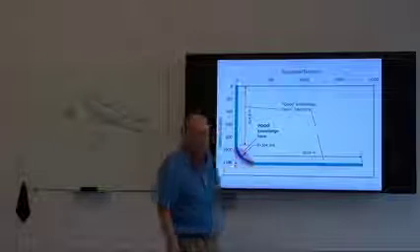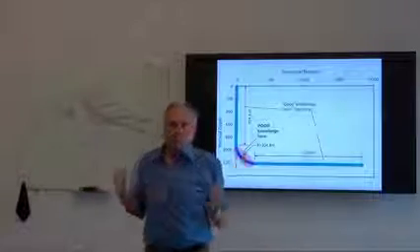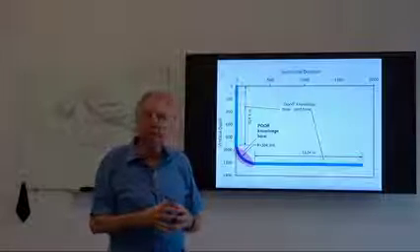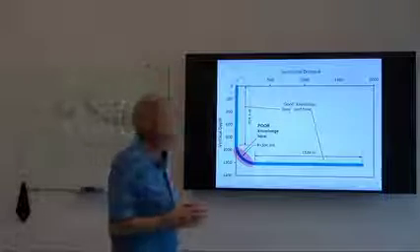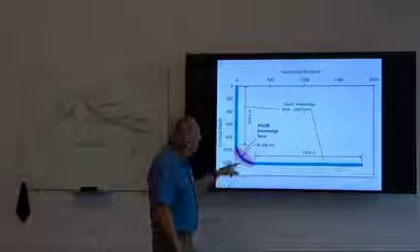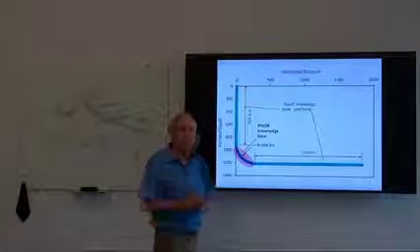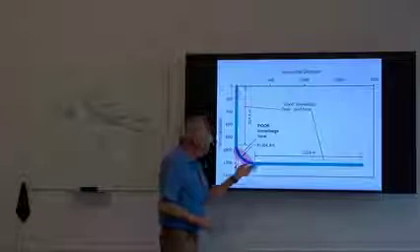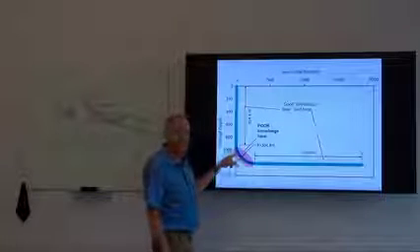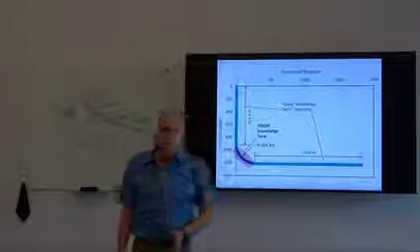Horizontal sections, well, think about a pipeline on the surface. We have pretty good knowledge in the industry about how to understand and how to model pipelines. So we have pretty good knowledge here. The tricky part is in here. The knowledge here has been quite poor overall. And when I say in here, I mean the entire heel in a horizontal, or any highly inclined section of pipe. This could be in an S-shaped well also.